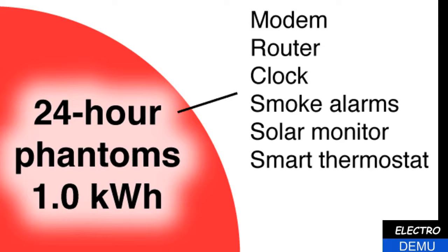the kilowatt hours is always a multiplication of the amount of current and time. In the past, we've been talking about stuff that have high currents, but the time is very low. Well, this one is the opposite. The time is very high and the current is low. So the final product is the same. And so these what we call phantom loads would actually add up to about 25 plus percent of your total loads. So the key point here is to unplug these phantom loads, and that will reduce your power source.